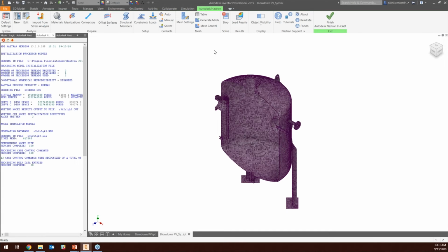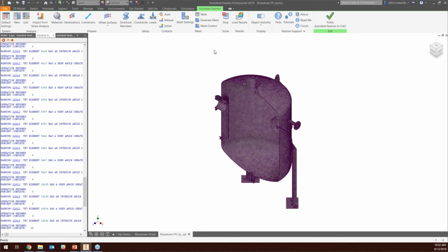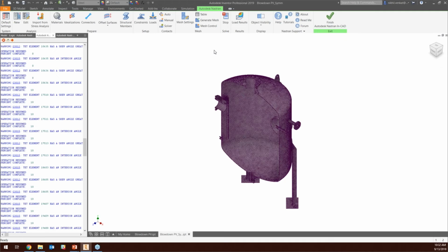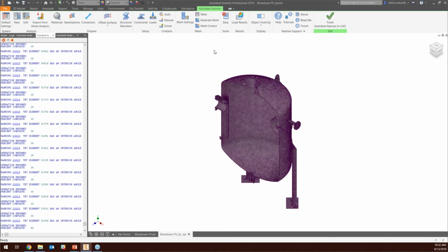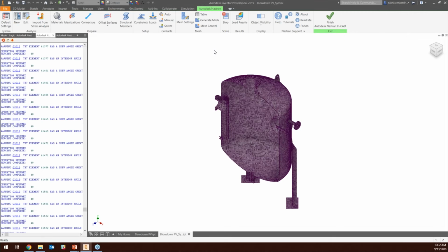I mean, you can include it. Yes, but it's not better than doing bonded connections, unless you are really specific about analyzing the welds, in which case I would recommend analyzing them separately. Trying to combine welds, especially if you are expecting to model the weld beads as solid models, usually doesn't end well.